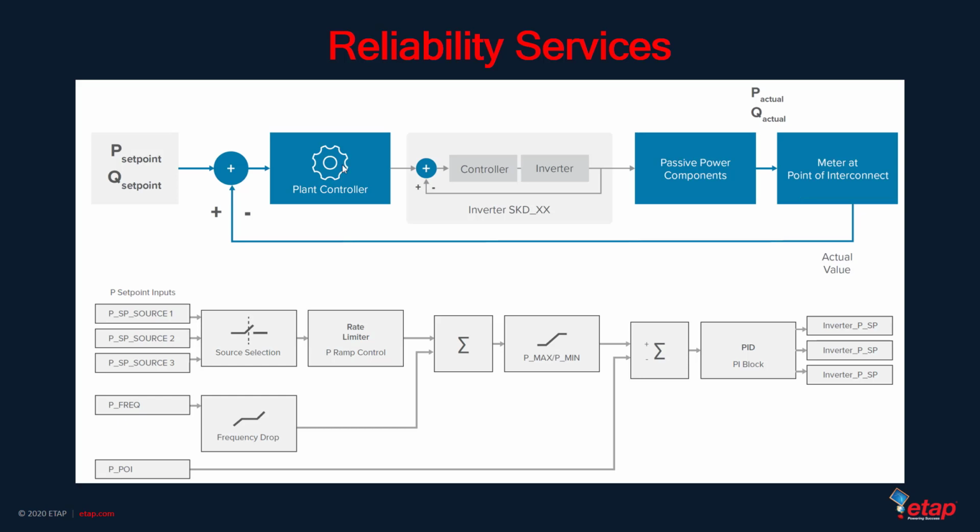The figure shows a simplified control logic for plant control. The source of the plant level set point, such as the P and Q set point, may be one of the authorized users sending a manual command. Changes in the set point from the user are passed through a PID control and through a velocity limiter. The PID controller constantly compares the current set point with the actual value as it appears on the grid. This is referred to as closed loop feedback.